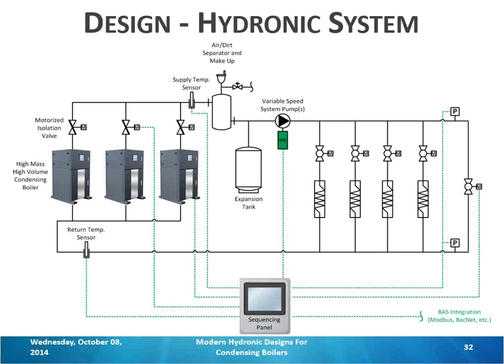Now we want to make sure that no valve goes full open and doesn't get enough heat, so the controller should be able to at least get feedback from those valves to make sure that none of them go to 100% while still lowering the temperature, because you need to keep all zones satisfied, right?